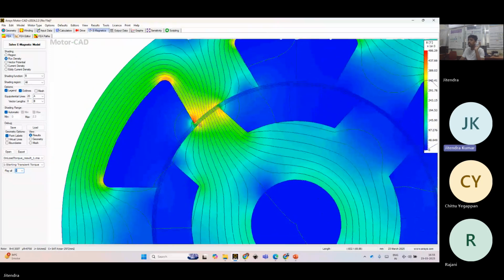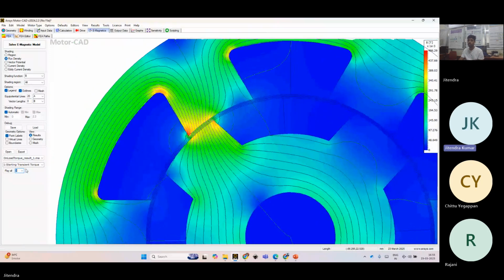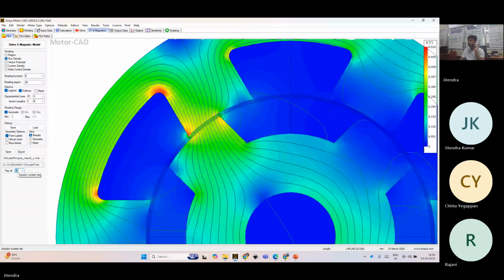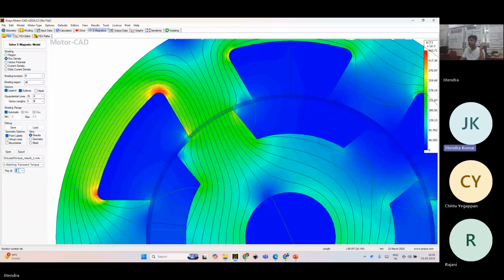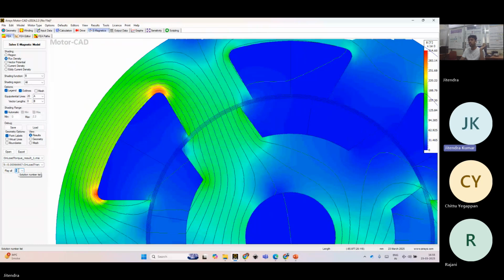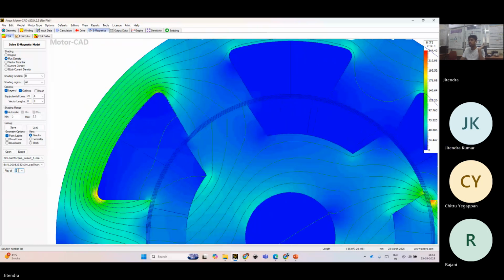So this is how flux lines basically look, what we were designing in the lecture. This is how it goes from unaligned to aligned. Now it is still aligned here. Now it is starting to get completely aligned, and where torque will be 0 for that phase. So that phase will go to commutation, towards the off, right?